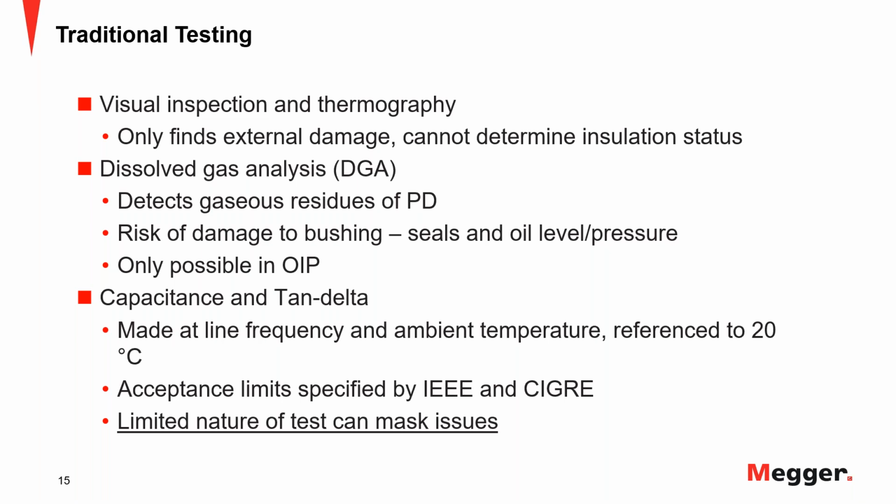The other one, for example, proposed by Segre, is to measure the temperature at the bottom flange and to measure the temperature at the header of the bushing. And again, you take an average between those two, depending on the length of the bushing. Segre has a little bit more complicated equation, but at the end, it is a tough question to determine exactly what is the temperature of the bushing, of the insulation.